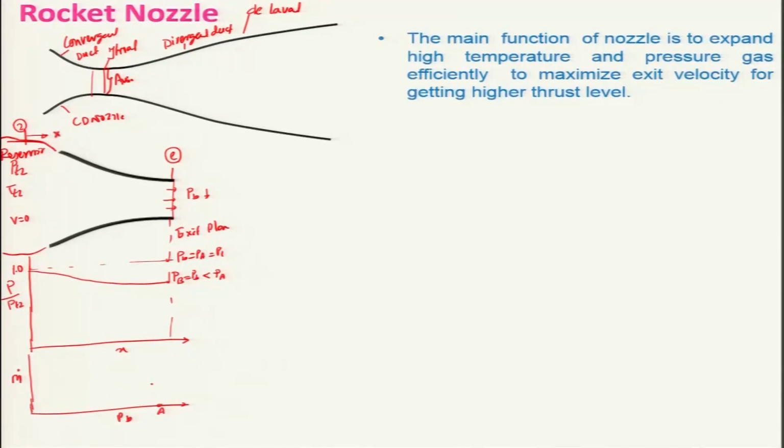So the flow will be, let us say, at this point B, and in this case the pressure will be changing as we have seen, the velocity will be increasing and the density will be decreasing because the pressure is being lowered. Then let us say a condition where there is a pressure PC lower than PB, then naturally there will be an increase in mass flow rate.